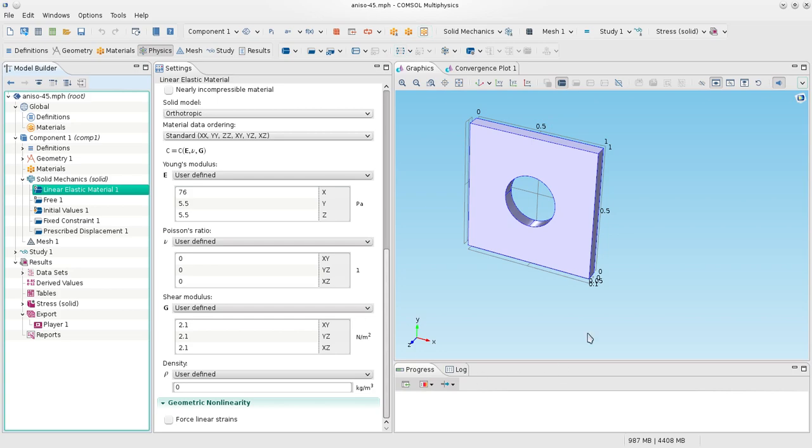Now I'll take a composite plate and cut this plate out at an angle that is skewed to it such that when I put this plate on this structural problem, the fibers do not run along the x direction, but rather at an angle that is skewed to the x direction, but still in the xy plane. So they don't have an angle with respect to z, so it's still perpendicular to the z direction, but they have rotated along the xy direction such that the angle they make with x or y is 45 degrees.